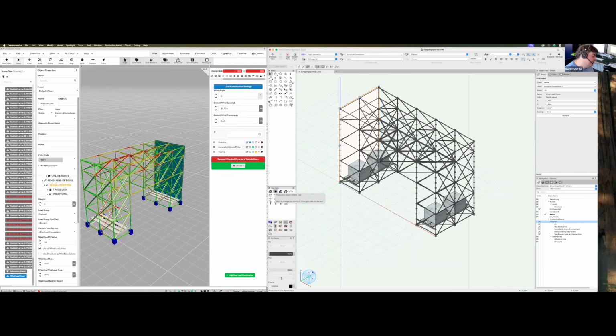A good example of where this applies is the OOE LED walls. They have one line which is specially optimized for wind load, and they actually made tests in the wind channel. They provide you with documents, and then you can take it over. But if you don't have any documentation on how this reacts to wind, you need to use the worst case scenario. Yep, understood.